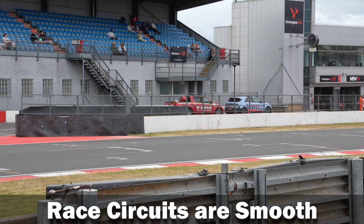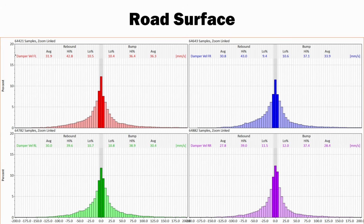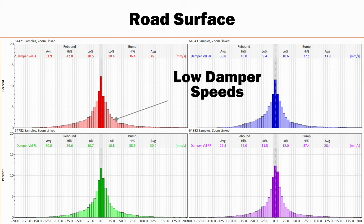That means for a race car, we've got a different approach to our suspensions. We're going to be dealing with generally lower damper speeds. It means we can run the car a lot stiffer. For a road car, the stiffer we make it, the less capable it's going to be as the roads get rougher. Now, we also noticed that there's safety implications.